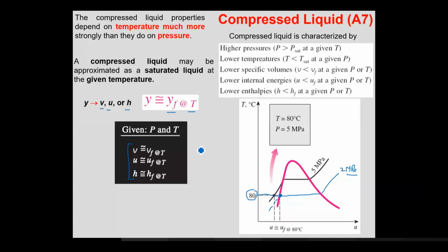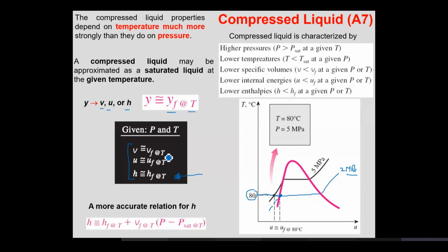Yes, sir. All right. For enthalpy, there is a more accurate approximation that can be used. You can use the earlier approximation also, but at times, if you want a more accurate approximation, you can use this one, where the first term is the same thing: h equals hf at temperature, saturated liquid at the given temperature. The difference is this additional term.